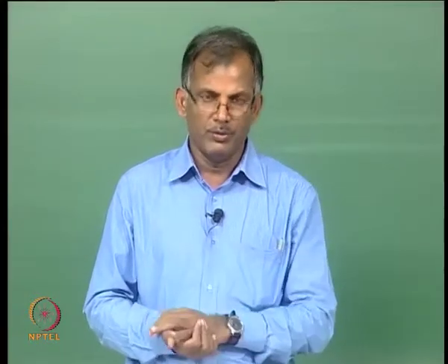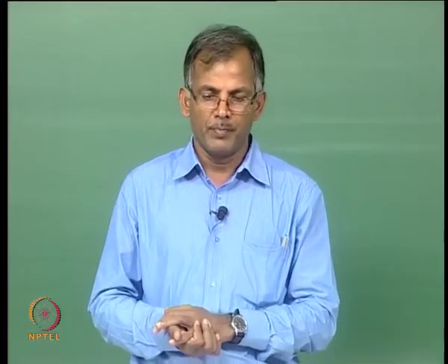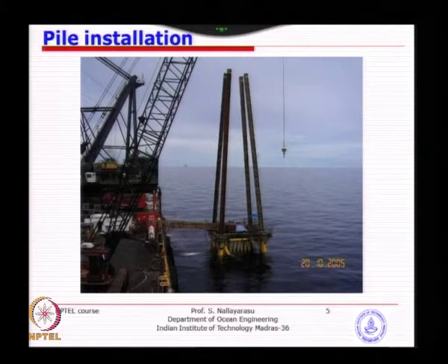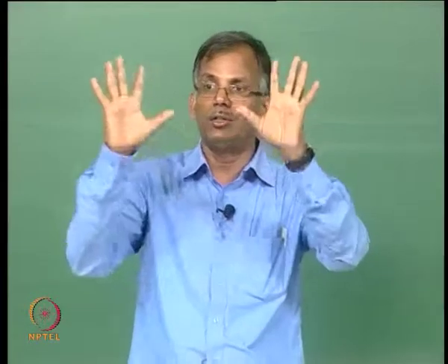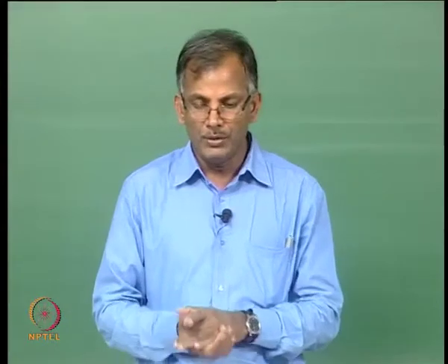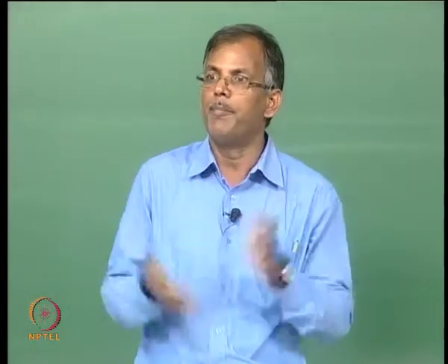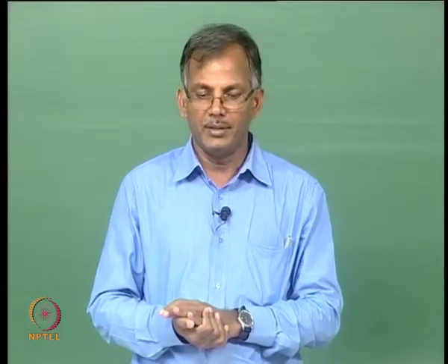We have a video, probably one of these days I will show you, that at that instant of time after the 4th pile was placed, it is still standing. A few seconds later, the whole jacket together with the piles just went down into the water, because of the stability of the system, because at this time no pile has been driven, it is only just standing there. So that is why sequencing to economize the driving time does not mean that you can place piles anywhere.